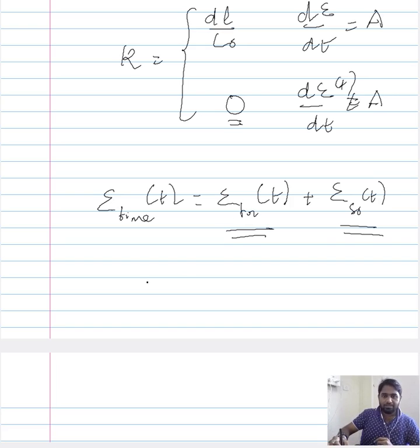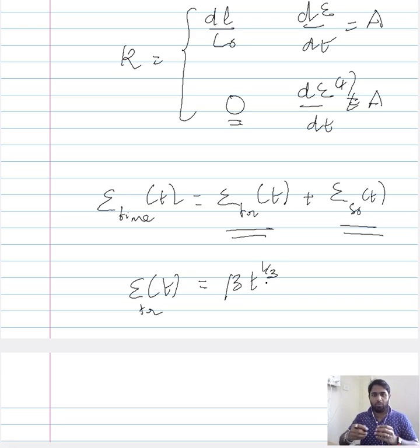Now this transient creep, the strain during the transient creep, was expressed by this factor, wherein again the strain during the creep is dependent on time. So there is a time dependent aspect to this strain in this period of creep, and it is related by this factor here, and this shows again a decelerating form of creep. And beta here represents the strength of the time. This coefficient represents the strength of the change in slope or the change in strain rate.